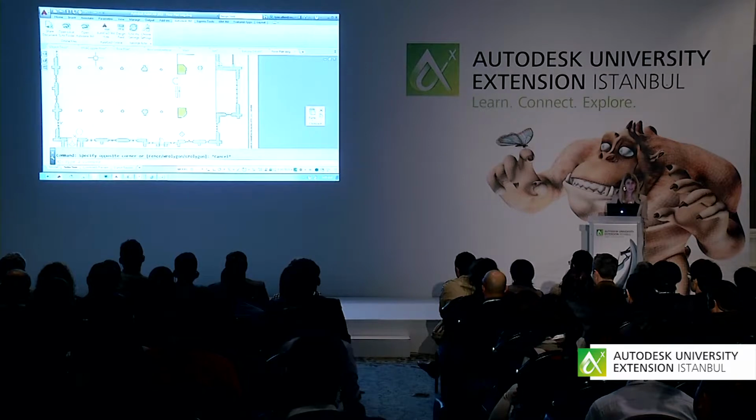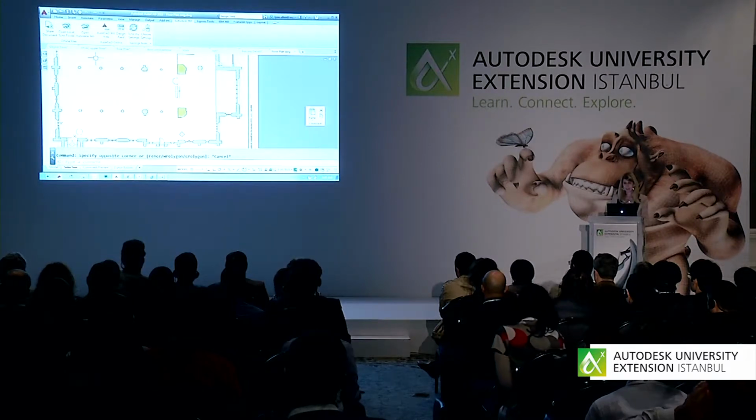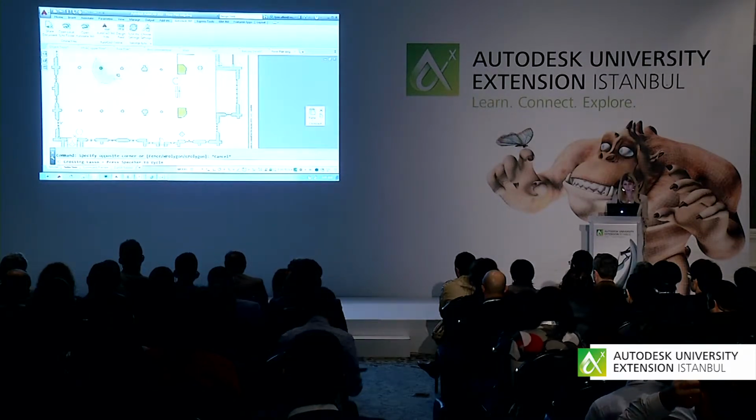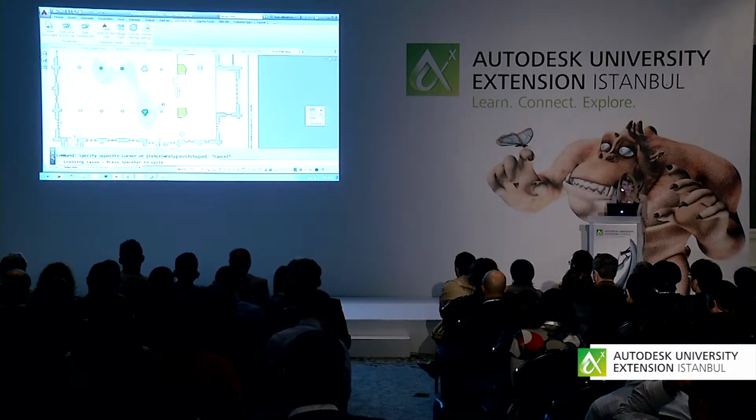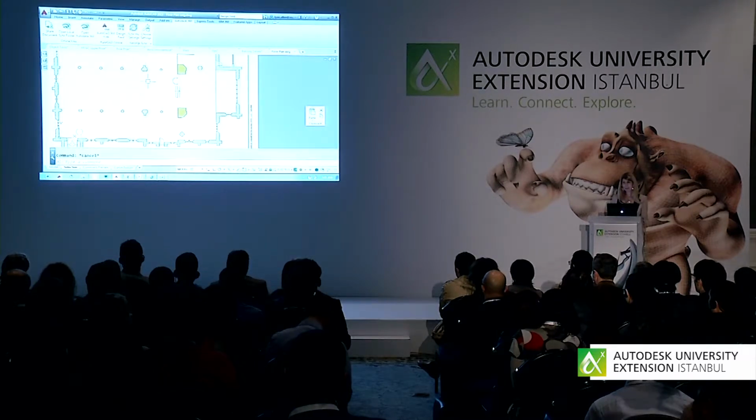So now if you hold down the mouse key, the left button on the mouse, you get something new called a lasso that allows you to be very specific in how you select objects. That's by holding down the left button on the mouse. If you go from left to right, you get a window lasso. If you go from right to left, you get a crossing lasso.